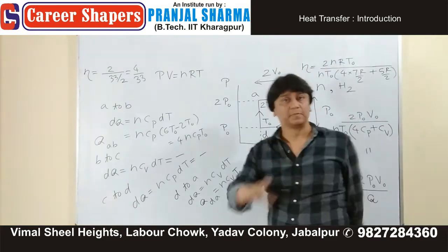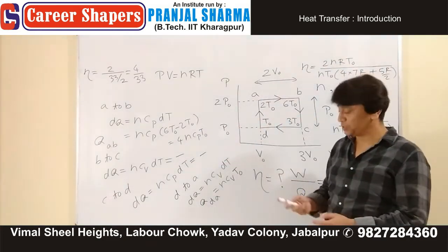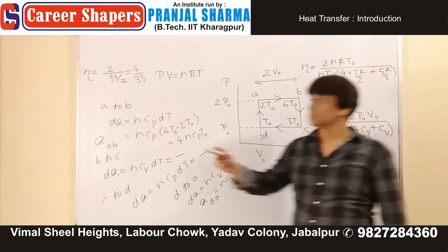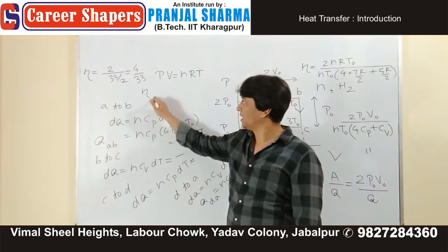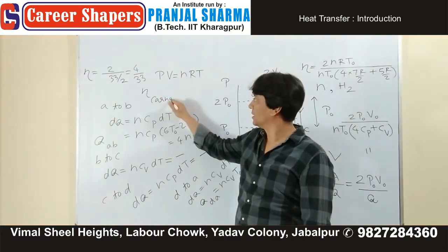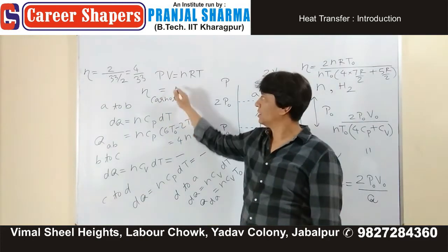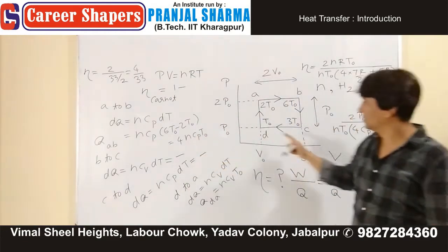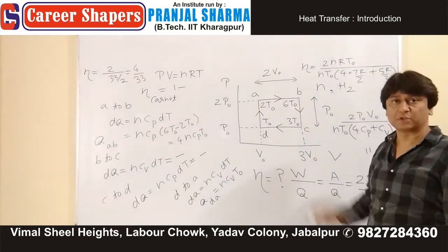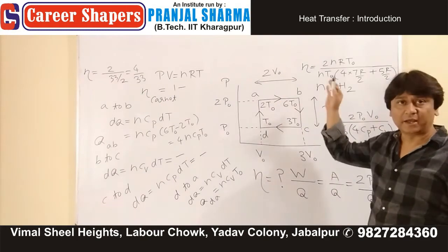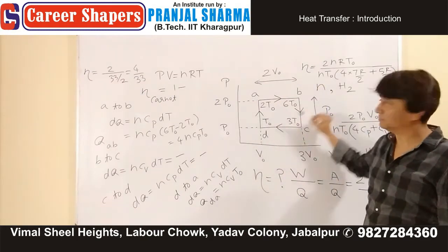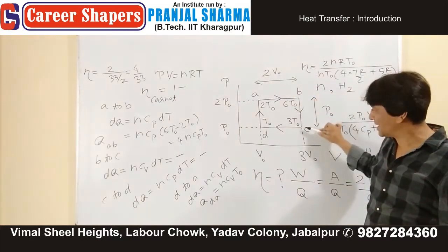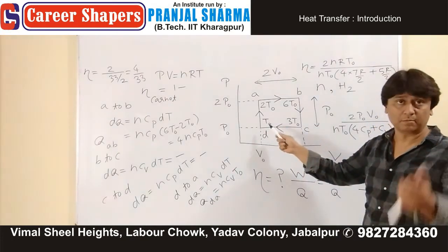And you can also understand one special thing with the help of this example. Had it been a Carnot cycle, efficiency is what? 1 minus temperature of sink over temperature of source. Highest temperature during the process, 6 T naught, that's your source. Lowest temperature, T naught, sink.